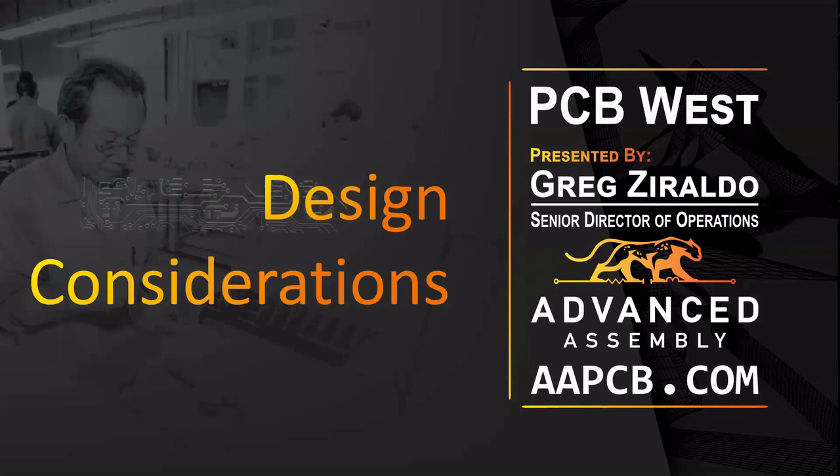So now that we've seen a couple of different things of what thermal expansion can do with copper on the PCB, you probably realize that it's best to avoid large changes and rapid changes in temperature. What temperature change you decide is appropriate for your design is a matter of design requirements and the material properties of the core material that you choose. Some important laminate properties to consider when it comes to protecting circuit boards, especially from high temperature situations, include a couple of key points and some definitions that are really going to help you in your journey as you go through this.